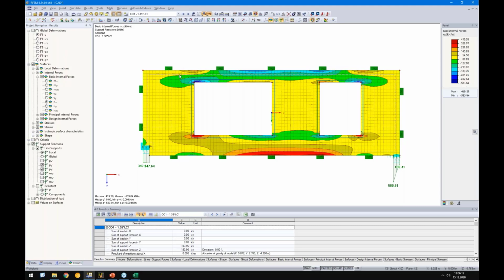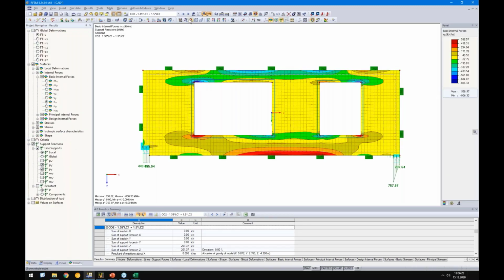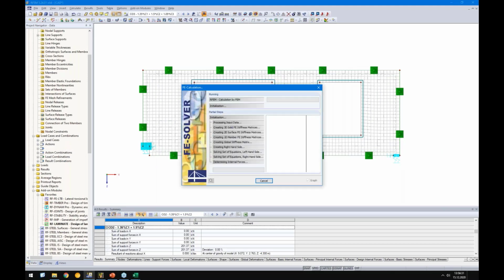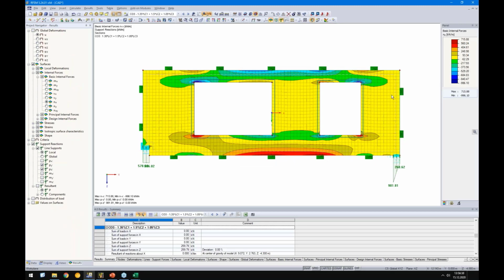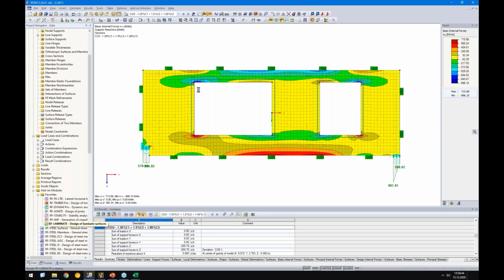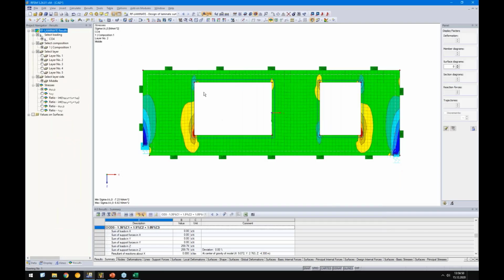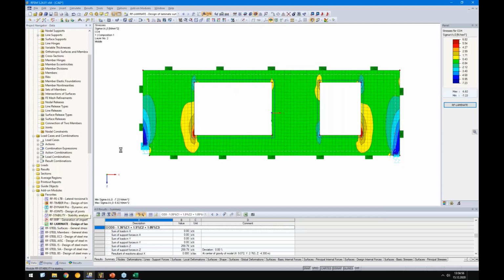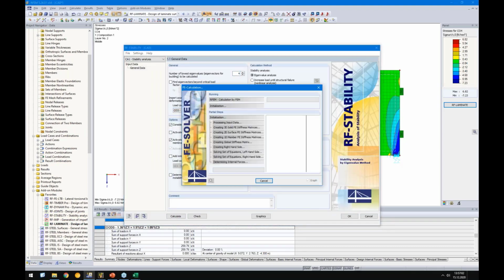Okay, we have around 580 here from CO1. CO2 is 806, and CO3 is 996. Okay, I guess the other one will not get any higher. So let's use CO3 with the highest normal force in this area, because I believe that the first eigenshape will happen here in this area, which is clear actually. Okay, let's go back to our stability and select CO3 and simply run the analysis.